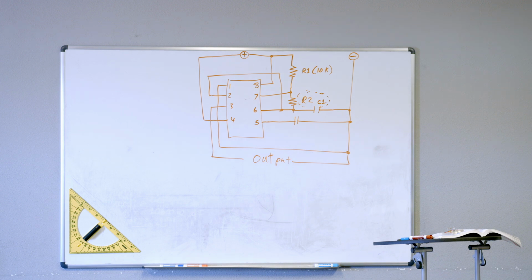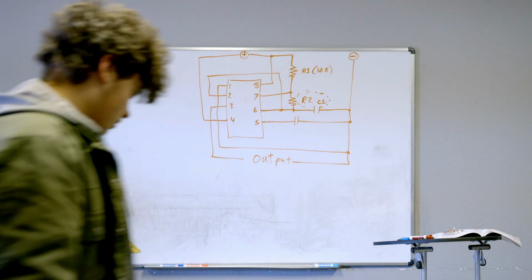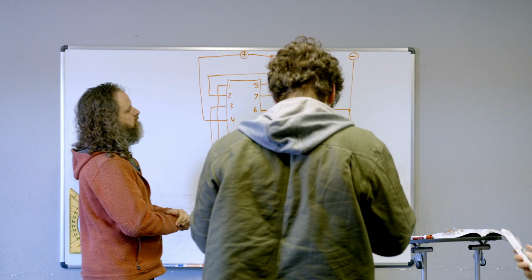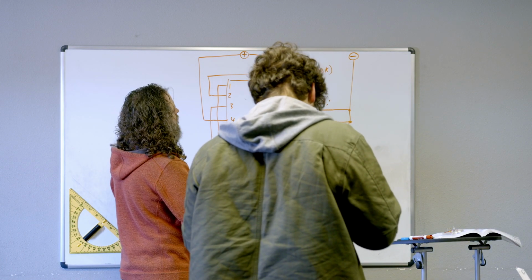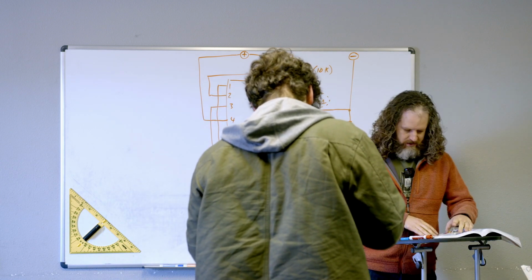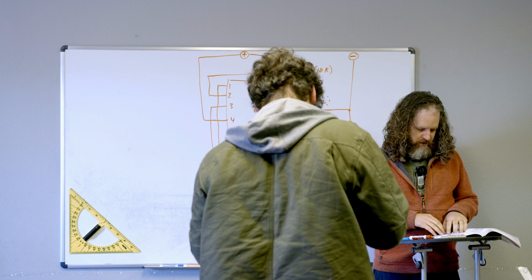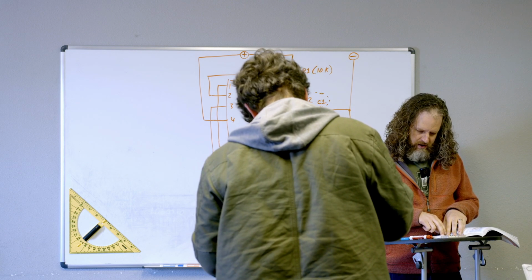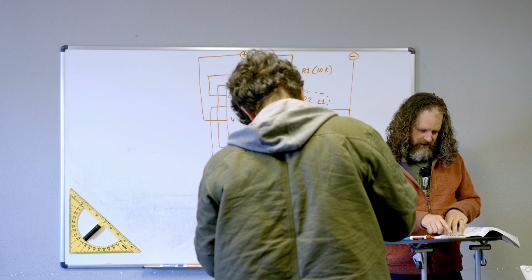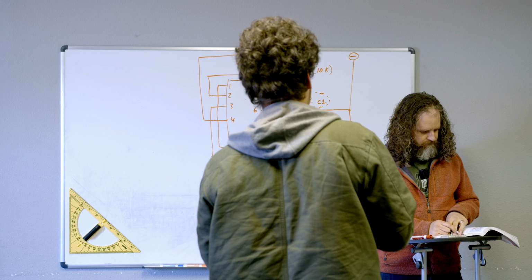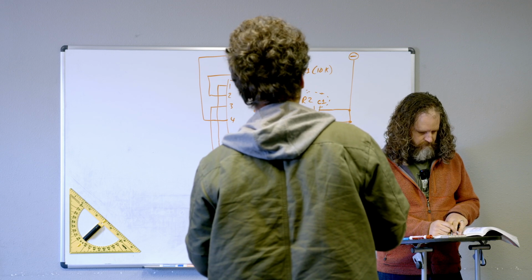Yeah, try to go faster instead of slower. Well, I did go faster. Is there a limit to how low R2 can be? So the lowest they list in their table, I'm sure that you could get a low enough number where it would not be so useful. The lowest number that they list is a 10K. So you could just get rid of it because there's already a 10K.